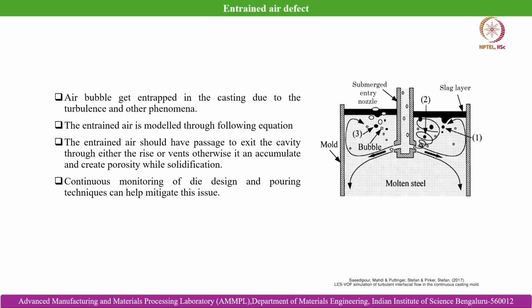In case of permanent mold also there are some, like we are creating the coating which gives it the smooth surface finish, and also facilitates non-sticky behavior of the solidifying melt with the die wall. Even these are a source of some gas evolution because of some amount of burning or sublimation, evaporation. So sometimes it becomes difficult, even if we perform the casting in a vacuum environment, then it becomes too costly.